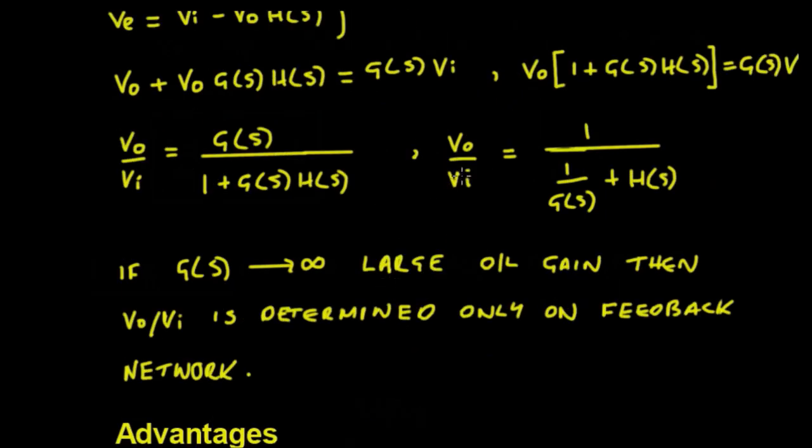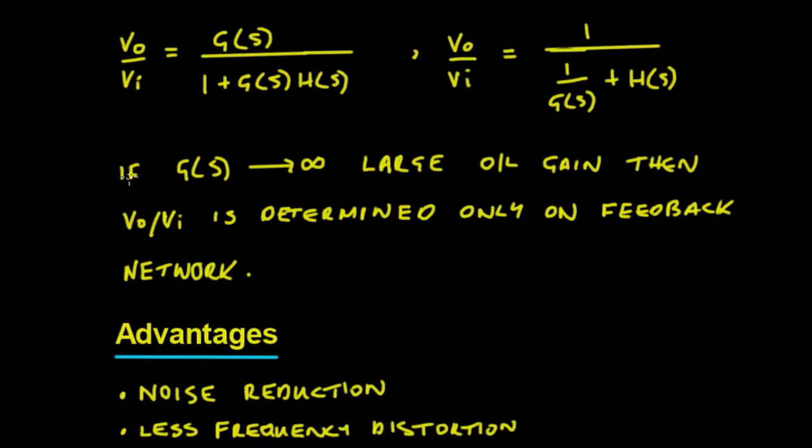So it means that we can rewrite that there if we divide it out by G of S by this here. Now we know, as we've seen before, that the gain of an amplifier ideally should be tending towards infinity, so that value G of S, the open loop gain, should be infinity, so that term there would tend towards 0.